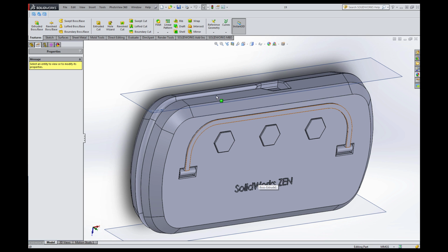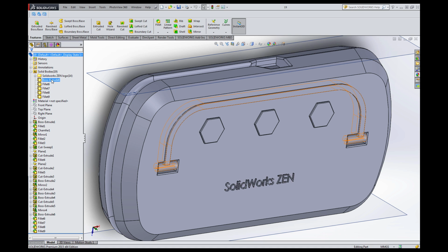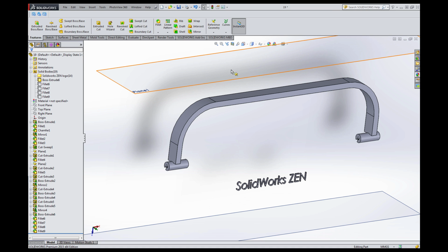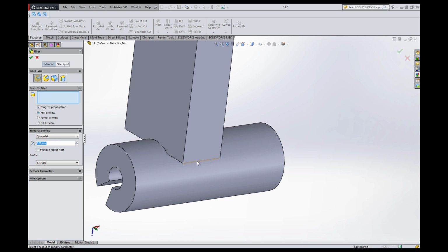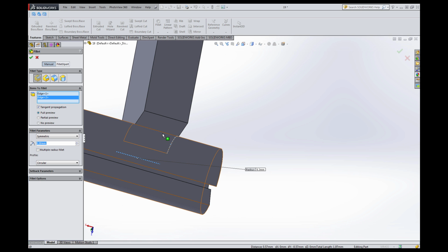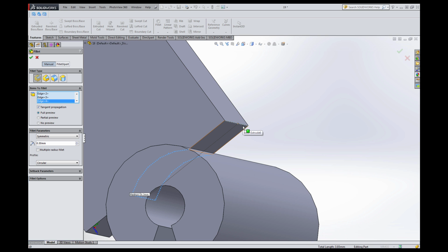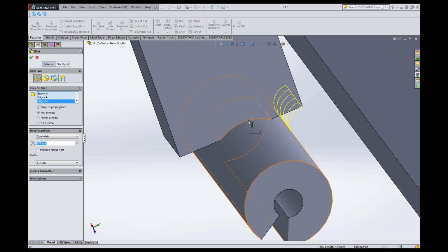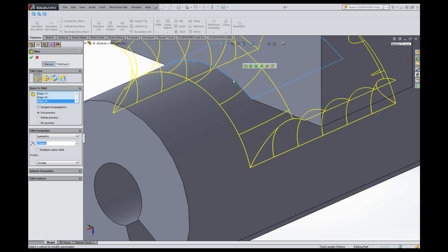Now I'm going to apply some filleting action on the handle. Okay, I go to solid bodies, and this is the handle. Okay, I want to hide all other bodies for now, so I'm going to choose this glasses icon. Okay, I want to make this handle more attractive by using this fillet option, and I'm going to put the radius of 0.3 millimeters and select some edges. Okay, 1, 2, 3 and 4. Okay, not this one, but this one. Okay, confirm.